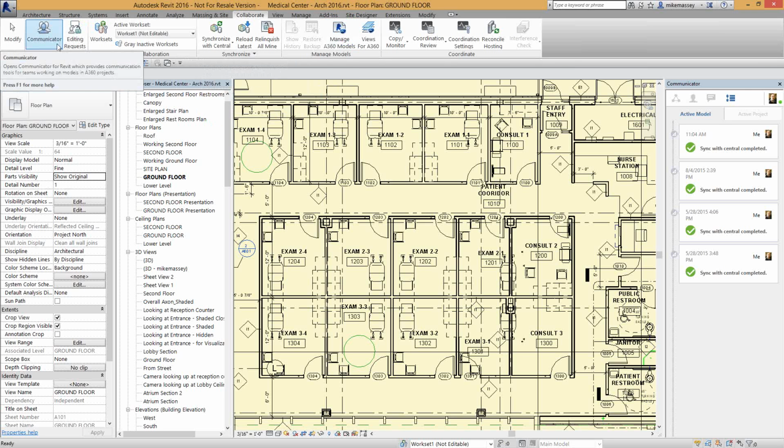You have to install the add-in. There is an add-in that you need to install, and it is specifically made for your version of Revit. There's a 2015 version and a 2016 version, but there's also a specific version for your builds. If you install something like Service Pack 2, there's a specific Collaboration for Revit install that works with Service Pack 2. So it does need to coincide.